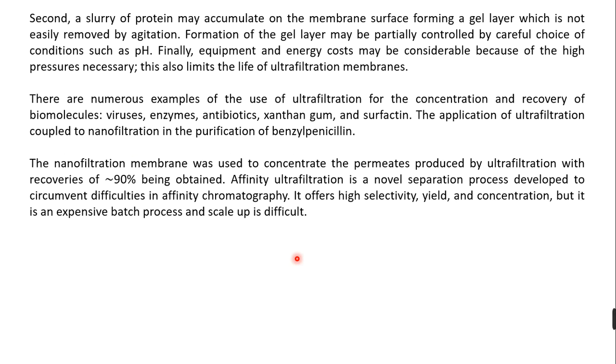The slurry depends. I already told you, if it has a large number of solid particles, that may clog the membrane, and the ultrafiltration membrane is very expensive. It depends on how perfectly you are using it, and how perfectly you are using the pressure. If there is any spike in the pressure, that may disturb or burst the membrane. So you have to be very careful, because this is time consuming and, at the same time, costly.